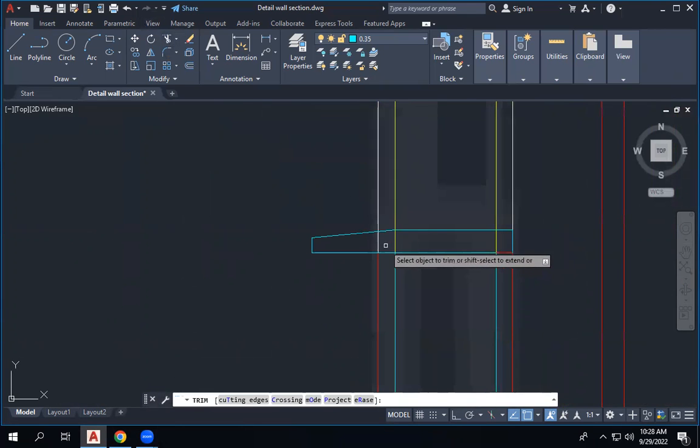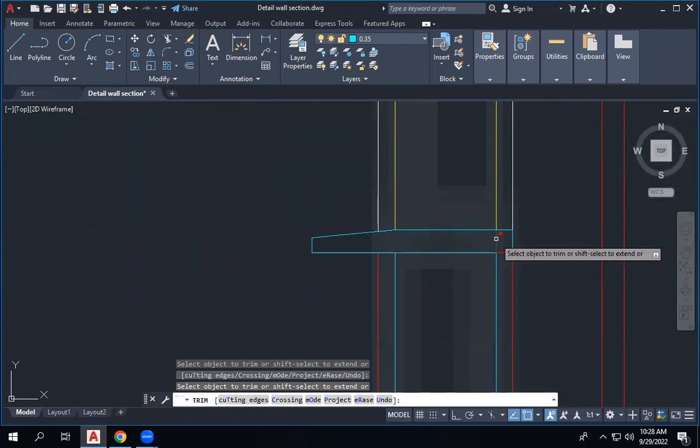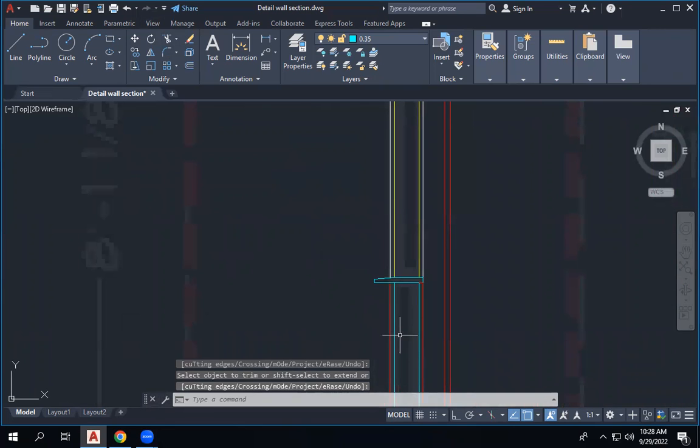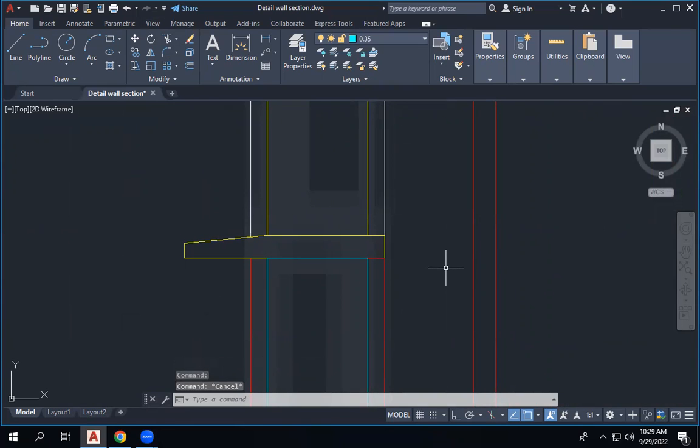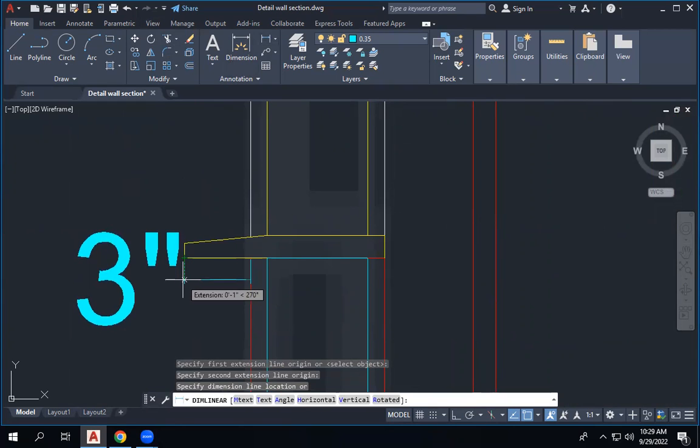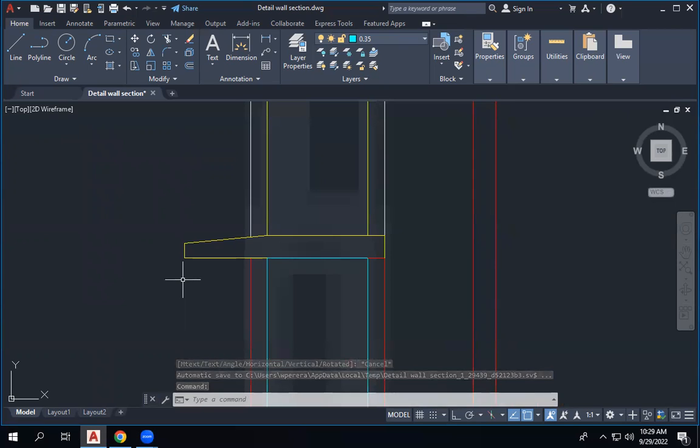And I'm going to trim these portions here. Yes. I'll just make this line 0.2. It's just take it 1 inch, 2 inch or 3 inch. So, yeah, 3 inch. Yeah, I took it as 1 inch, and it should be thinner on this side. The surface should be slanted outside. And what will happen is when the water falls onto this surface, it will come up to this point, and then this will work as a drip edge.